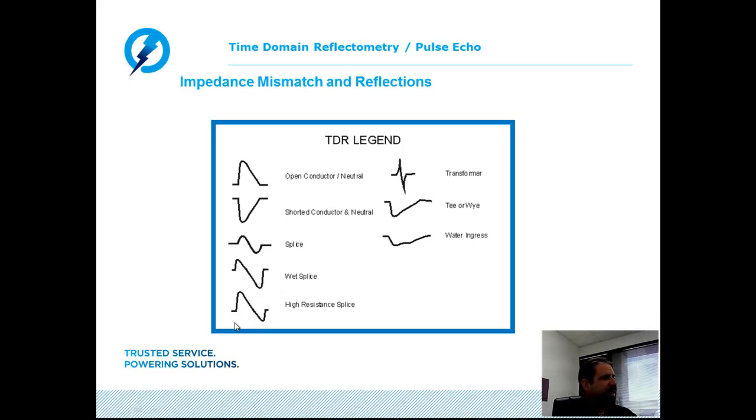By the same respect, if the conductors are starting to pull apart out of the splice, what we start to see is an increasing growth of insulation, or excuse me, of metallic resistance at the splice. So again, the up followed by down pattern typically is a splice. If it's bottom heavy, we can normally blame it on water. If it's top heavy, we can normally blame it on either corrosion or the actual conductor starting to pull apart.